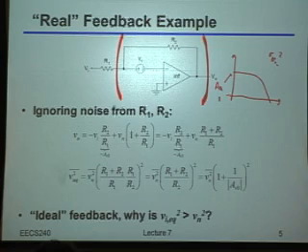The reason I mention this is that if the input you're feeding into it is a current, and you were going to input-refer the noise of that thing, what would be the dimensions, or the units, of the noise you would use? Yeah, you'd be doing things in amps, not in volts.